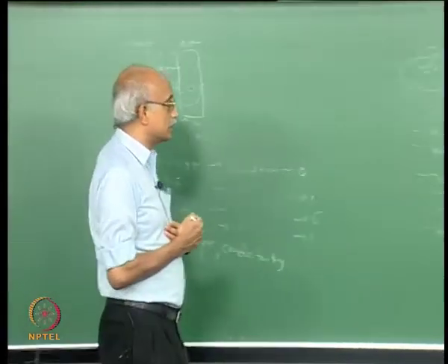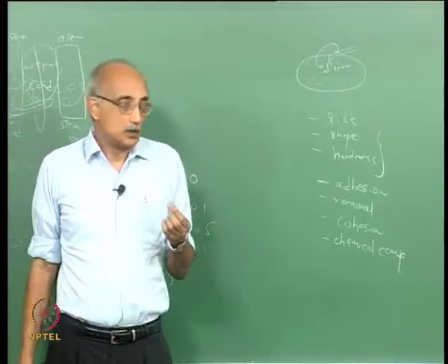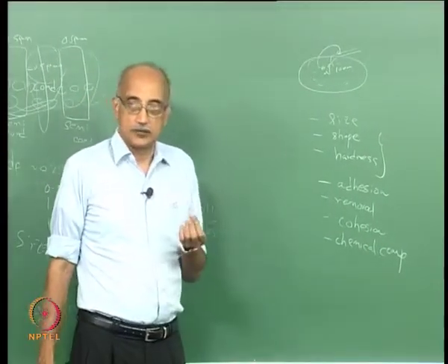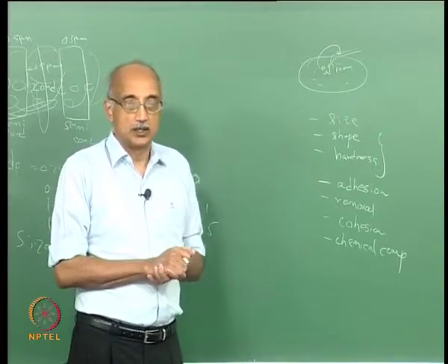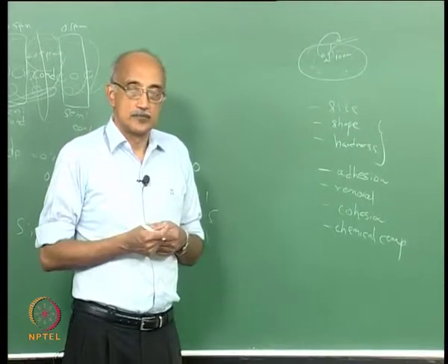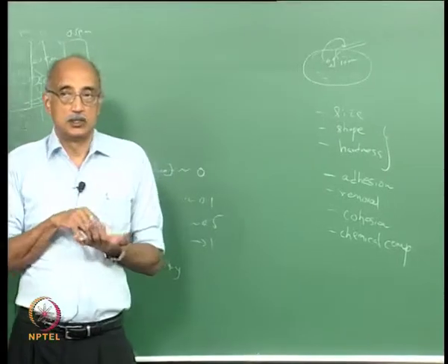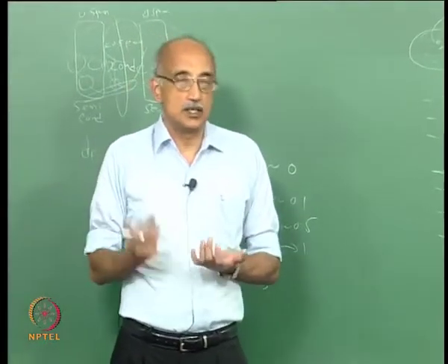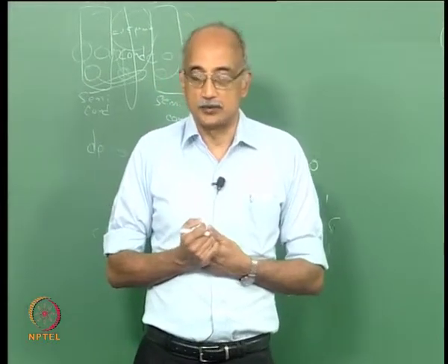Similarly, in the case of the disk drive, if a particle is only temporarily present on a critical surface, and then it gets dislodged because of the airflow or the movement of the head or whatever, then it's not something we need to worry about. It's only particles that stay on the device for a long period of time that really increase the probability of failure to virtually 100% probability.